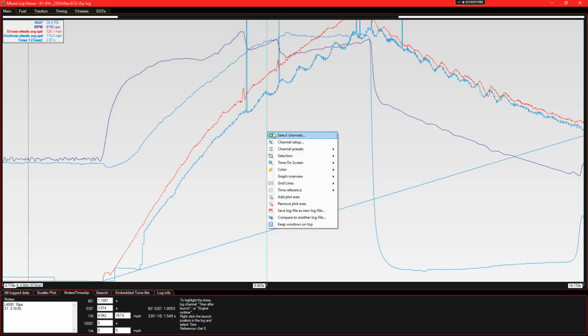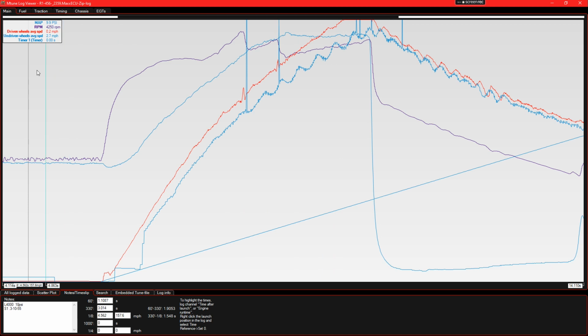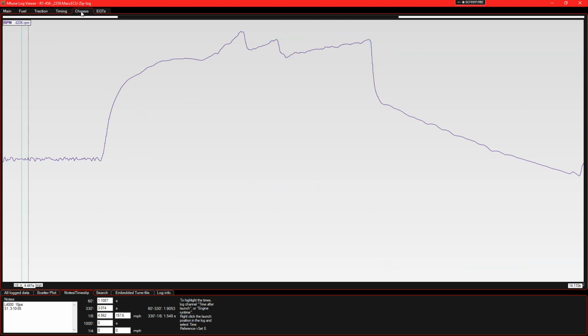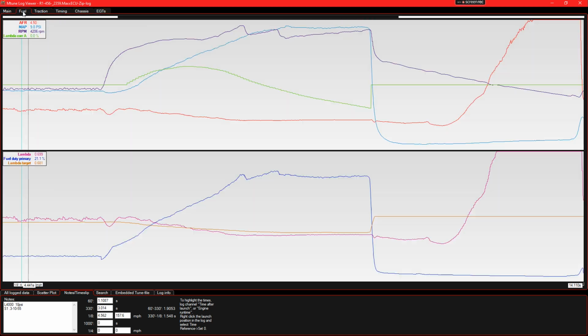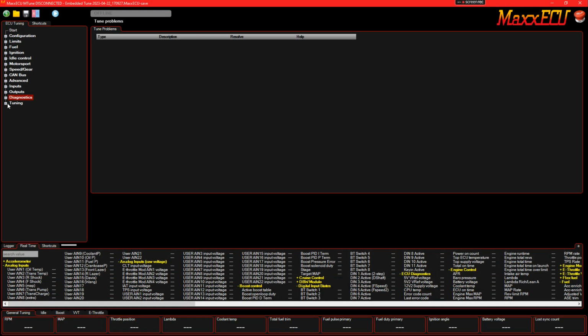And you can really set up parameters on all of your data log, like your channel setups. You can go in here and you can set the range, like RPM range 0 to 9,000. You can just do this on everything. So a lot of cool stuff you can do here. You can even program different folders for different things that you want to see on your data log. But anyway, that was just a quick rundown. I just wanted to run down the basics of the system without getting too complex with it. But there's so much stuff you can do with this system, it's unreal.